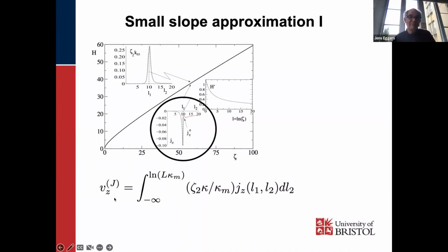So let's consider two integrals as examples. Let's first look at the J integral here, which represents the action of surface tension. That's why I have the curvature kappa appearing, and I have to perform a convolution of this curvature with this kernel J, which I'm showing here.